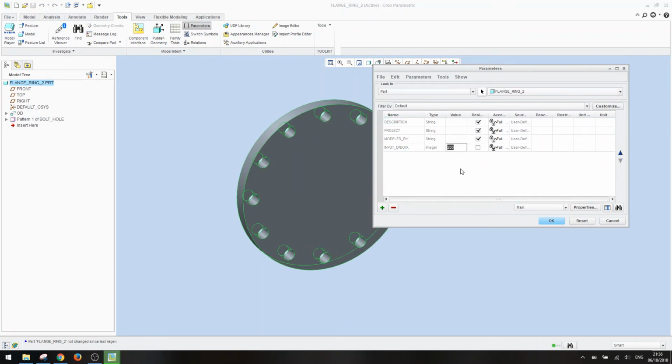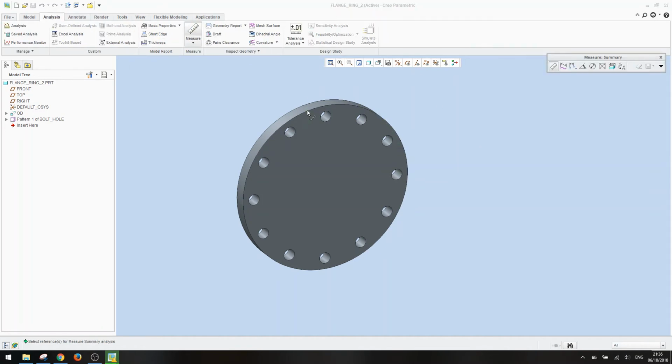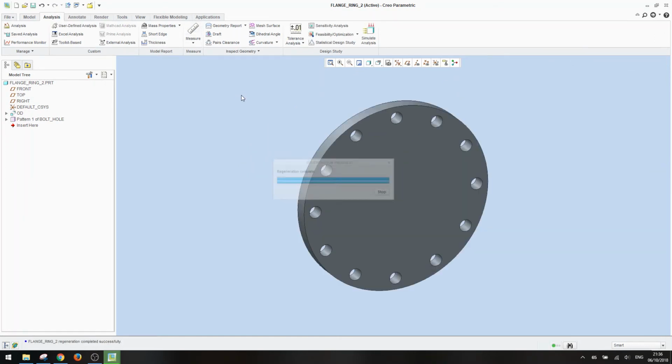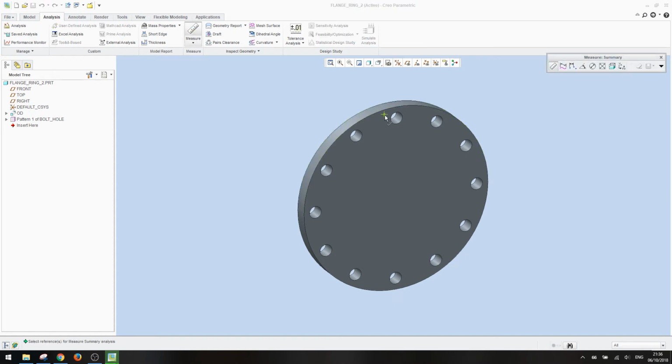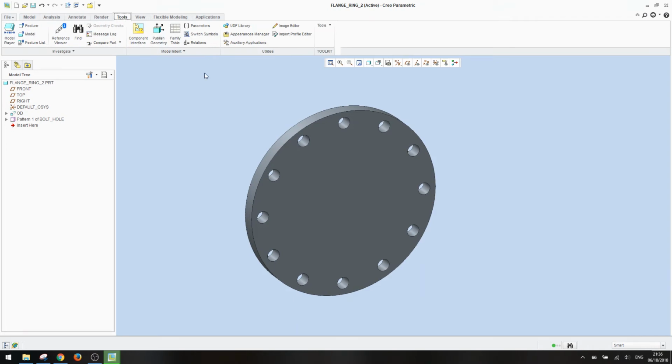So we've only got 200 and 250 sizes in. Obviously, if you want other sizes, you need to put them all in, as we just did. But I'm not going to go through all that because it's pretty long-winded, and it's basically a case of copying and pasting and putting new values in. Okay, so I'm going to go 250. Let's change that. Won't do anything immediately. I'm just going to take a little measure here just to show you something changes in case it's not obvious. That's 340. If I regenerate now, it has actually made that bigger. So now we're up to 405. Not always obvious to see with that one because it zooms the view. Okay, and I can change that back to 200 and it will switch back.